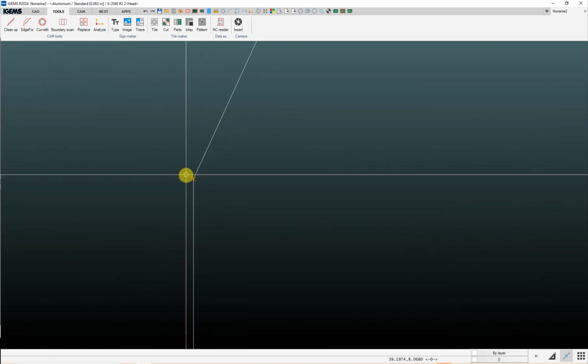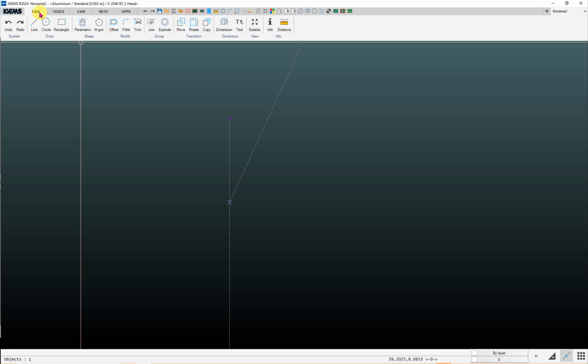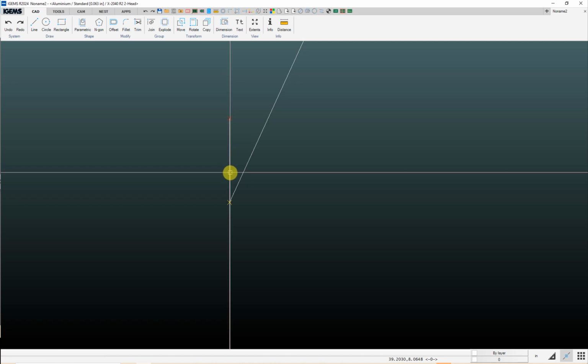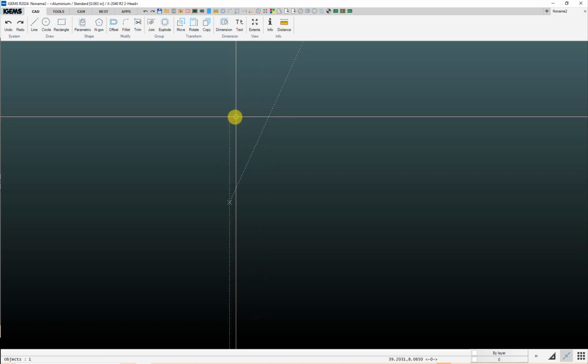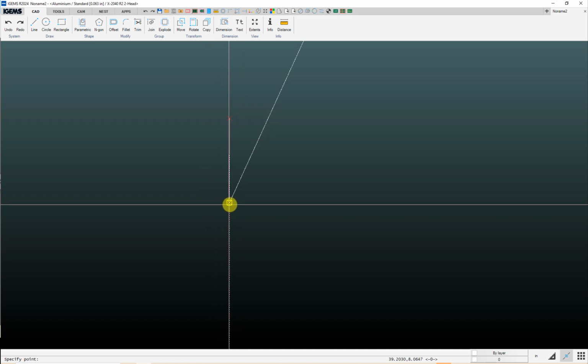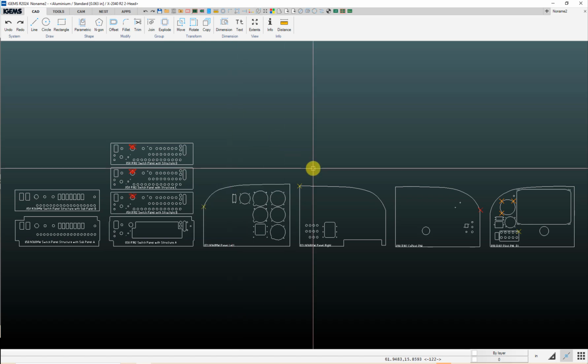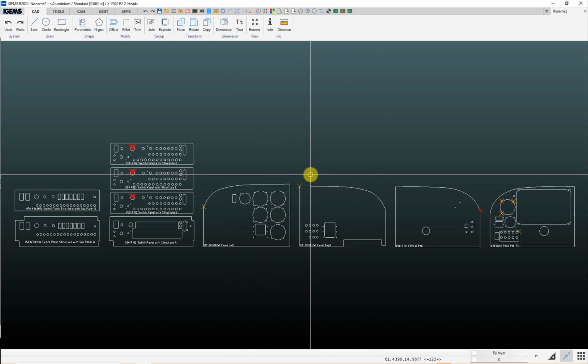If we look over here, there's a line that needs to be trimmed up. You've got two options on something like this, CAD and trim. You can click on that, get rid of that. So that's one option. Hit escape to get my trim command. If I click on the line, when it's highlighted like that, if I click on that blue grip, since my end snap is on, when that end snap shows up there, I can left click and move that point down there. Let's zoom extents here. We'll come back and do the Analyze once I think I've got things cleaned up.